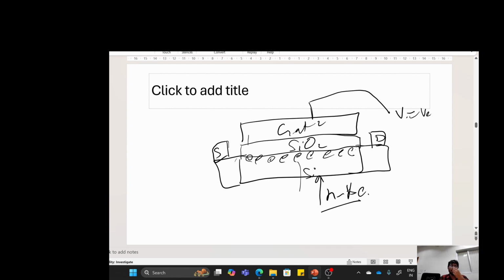So our FETs in our devices, in our mobile phones, are not used in this way. This accumulation mode is not used, depletion mode is used. In this case the current would flow through the bulk because there are electrons and it is n-type also.